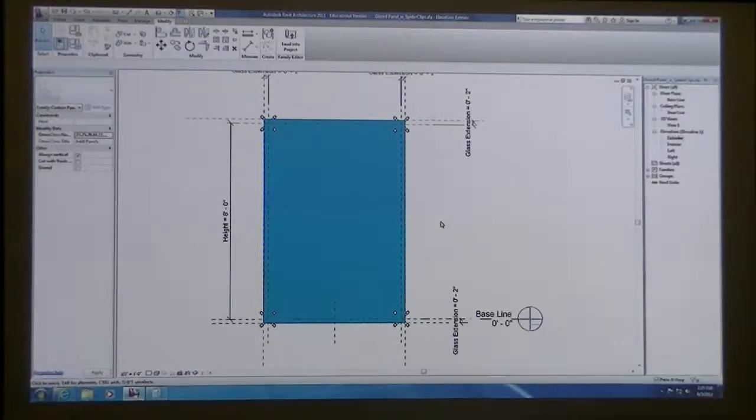when you started with your overall reference lines, did you have them far away and at least 1 foot away? If you happen to have them real close to the reference plane, it could be that Revit's getting confused with where that glass is supposed to be locked, and you're kind of over constraining the sketch is what it's saying. Sometimes you get that and it's frustrating, and you kind of have to back away and start over, maybe delete those dimension strings and just go far enough away.